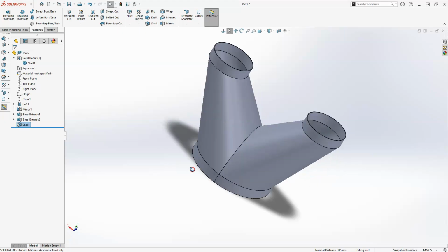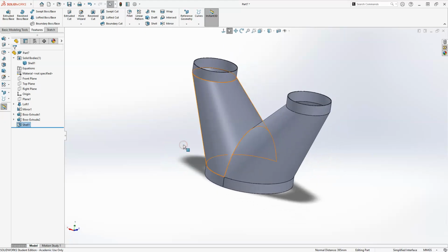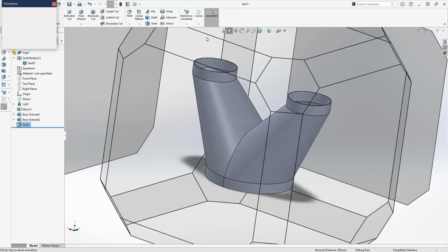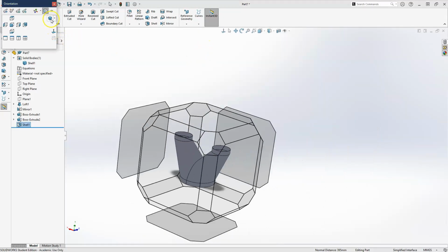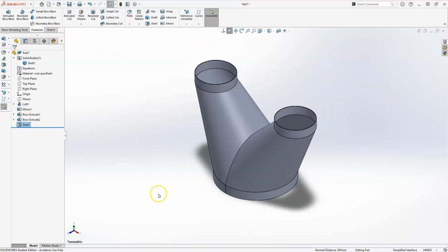All right, so hopefully you enjoyed this short little video. The most important thing to remember is that anytime you want to create a loft, just remember multiple profiles. Luckily for us, this one only had 2 profiles, but there are some more complicated lofts. Sometimes it's easier to create it in another program, and what I usually do for more complicated lofts is I'll usually open up AutoCAD and I can sketch it out in there really quick, and then I'll convert it and bring it over to whatever program that I want to use.